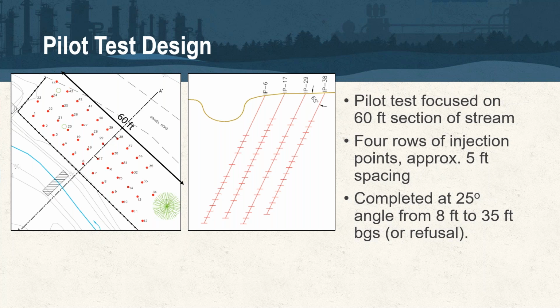The other thing is where you've got a very limited number of samples and you're trying to correlate that data. It's really difficult to do on most sites. And I think the folks that work with those tools every day would tell you the same thing, that it's really hard to correlate. You've got to run those in separate paths, and then you can draw some correlations if you have a dense enough data set, but you can't go out on a site where you've done 2 weeks of MIP and grab 3 soil cores and a couple grab groundwater samples and expect to correlate that and come up with a remedial design.